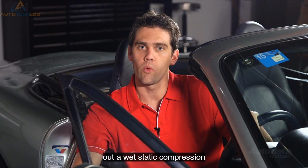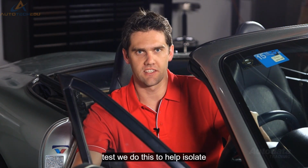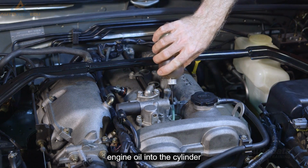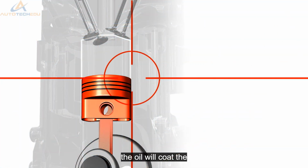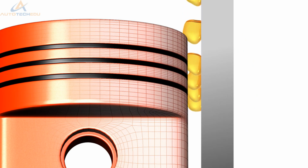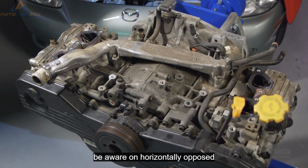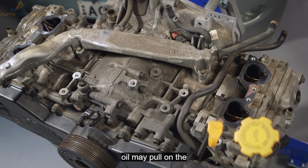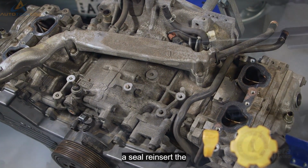Next, we'll carry out a wet static compression test. We do this to help isolate the fault. Put a small amount of low viscosity engine oil into the cylinder that you are testing. The oil will coat the outer edge of the piston and rings, creating a seal with the cylinder bore. Be aware, on horizontally opposed engines, that this might take a few attempts as the oil may pool on the lower side of the piston, making it hard to create a seal.